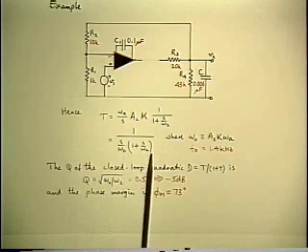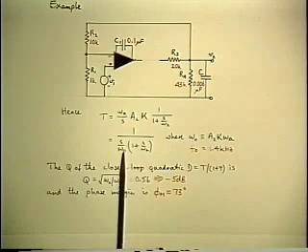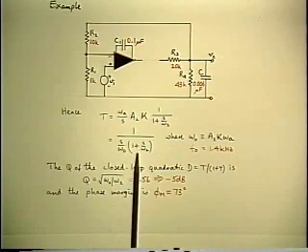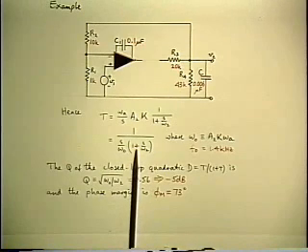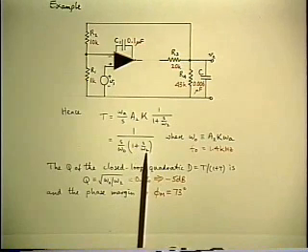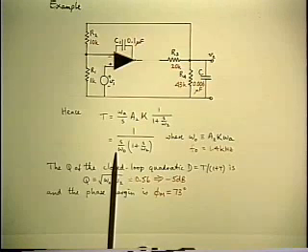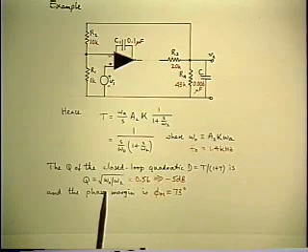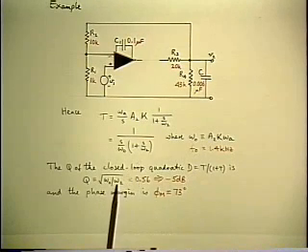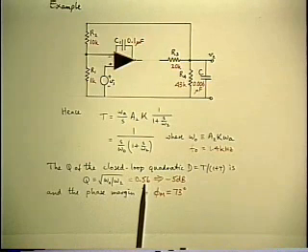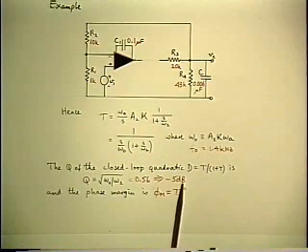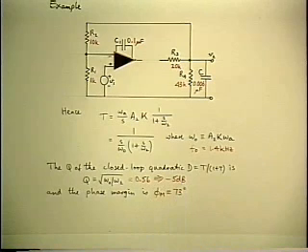We know the closed loop gain is going to be flat, but it's going to roll off according to a quadratic, and the Q factor of the quadratic is determined by the position of the second pole relative to the crossover. And the definition of the Q is omega 0 over omega 2, which in this case is 0.56, or minus 5 dB, which means it's barely into the complex range.